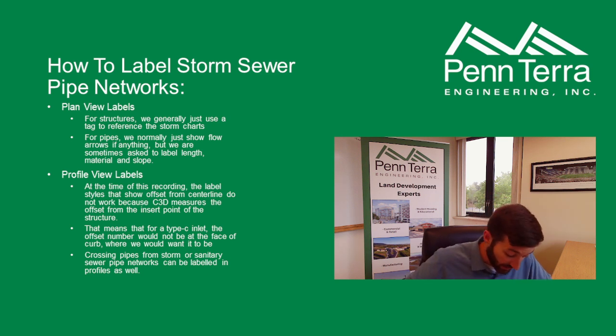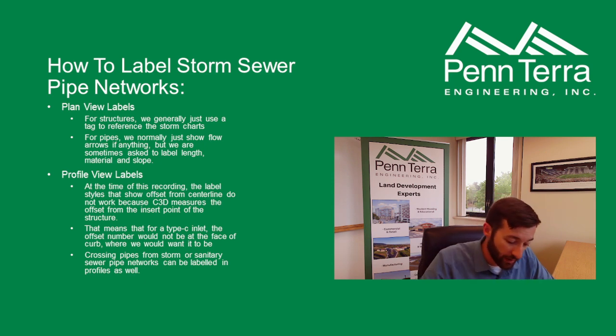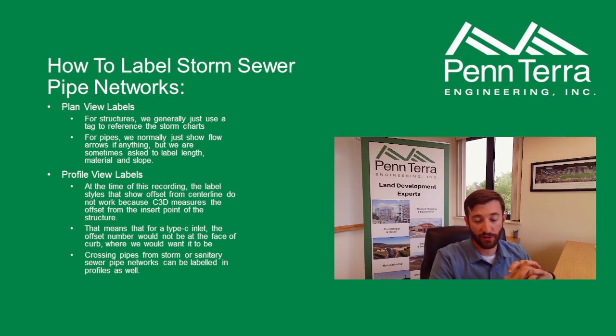Okay, next is labeling. Labeling for storm sewer pipe networks is basically the same as labeling for sanitary. So generally in our plan views, we just use tags of the name of the structure for storm, since we have storm charts on almost everything we do. For pipes, we usually just put flow arrows because that's required, and we don't generally put the length, material, and slope because it becomes kind of a nightmare with text conflicts, and that information is also in the storm chart.